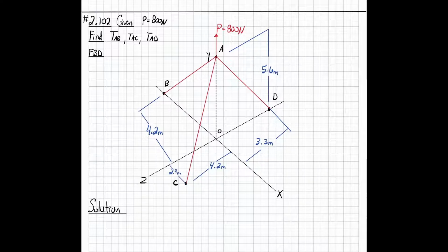On problems like this one, on the exam, there's not a whole lot to do for the free body diagram, other than taking the same diagram that they give you and drawing arrows in the direction of the tension or compression. So what I currently have stated is a tension from A to C, so it's pulling away.